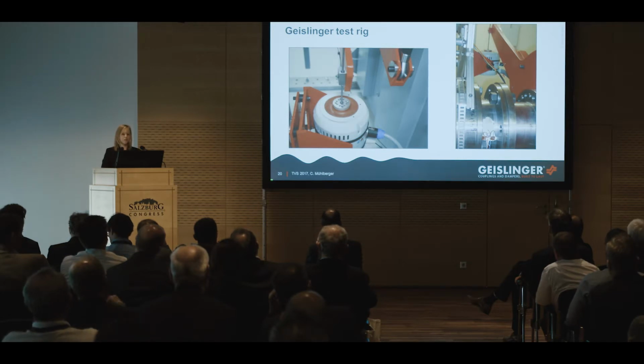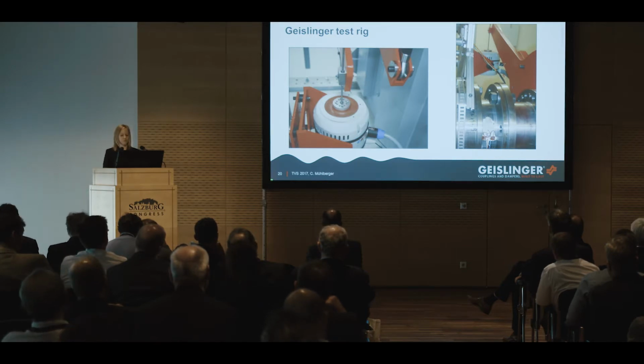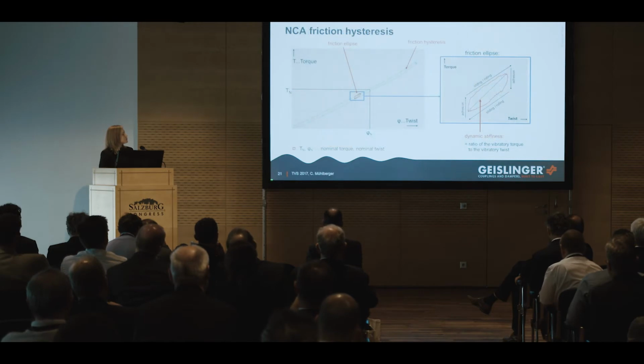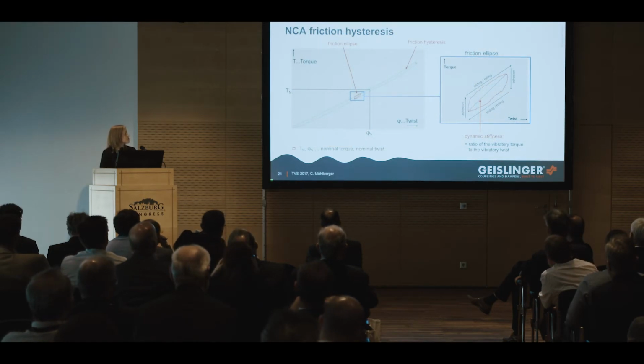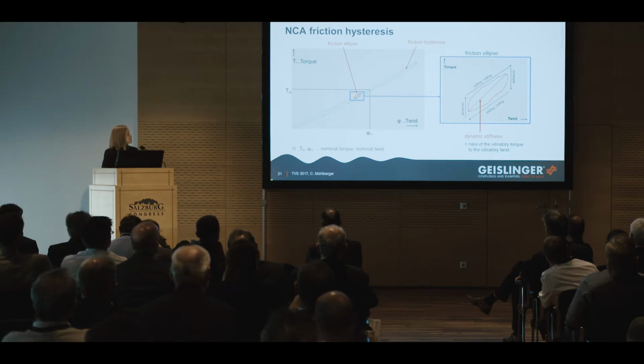I would also like to mention that for all of the following test results, we did not measure with a pressurized oil supply, which means that hydrodynamic damping can be neglected, and we only focus for this part on friction damping. So the first main result is this friction hysteresis, as Mr. Hassan already talked about a little bit.